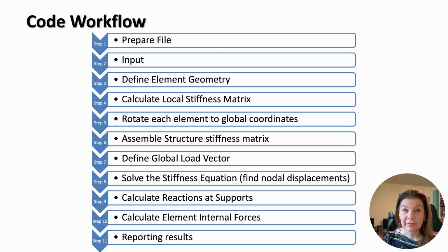When we were building the theory, inputs naturally appeared at the moment they were needed. In actual coding practice, however, that leads to inputs being scattered throughout the script. So in this final version, all the input information is grouped right at the beginning: the node coordinates, the connectivity, the material, the section properties, the loading, etc. It makes it much easier to see where everything goes, and also easier to adapt the code for other structures. So just to be clear, this reordering doesn't change the method at all. It's just cosmetic and makes the script more user-friendly.